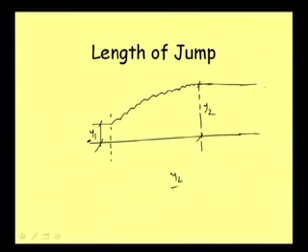Then we can try to measure y2, so we can apply both points, that is, our observation and the calculation. There will be some error in the calculation of y2 as well, because in practice we are neglecting friction in this formula, y2 by y1 equal to half of root over 1 plus 8 F1 square minus 1.